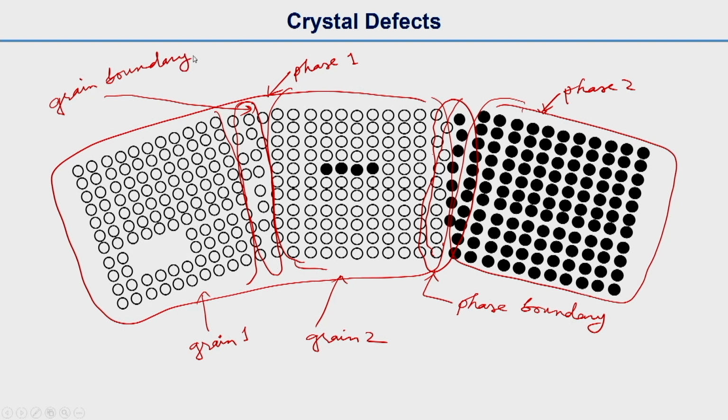Grain boundary is also a crystal defect, as we have discussed, a 2-dimensional crystal defect. Similarly we have a vacancy zone. This is a group of vacancies, or we can call it a zone of vacancy. As I already told, these 3 figures, these 2 slides and the earlier slide, are from Marc Meyers' book, that is figure number 13.7, zone of vacancy. And similarly there are some foreign atoms that group together, so we can call that a zone of foreign atoms.